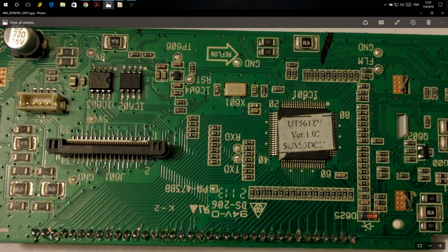Do I have 8 volts at the pads for that? Do I have these voltages? If I have these voltages, the third thing, believe it or not, that I'm going to check is: is my reset high or low? If it's low, then I'm being held in reset. So why am I being held in reset? Is it because my supervisor IC has failed, or is it because my microcontroller has failed?